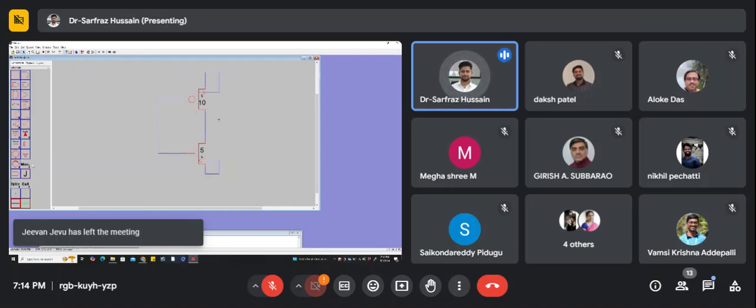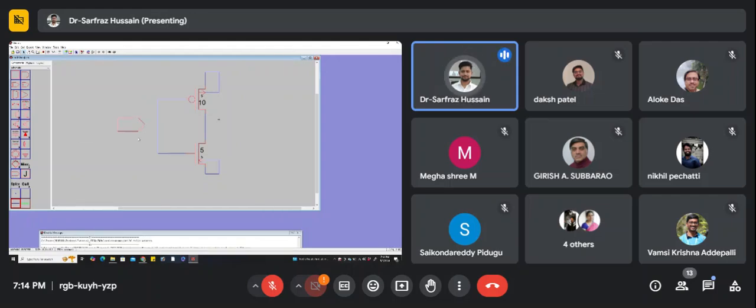Okay, fine. So what we can do is choose some pins for this, and we can have this one as the input and output. We can do it by putting some netlist like that. For the pins, you can just select this and place it over here. So this is basically a pin. Here it can be an input pin or an output pin. So let us first place this pin, and then we'll drag it and connect it.